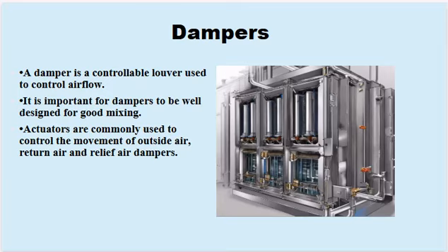They're typically installed within the ductwork to adjust the amount of air flowing to specific areas. Firstly, dampers work by opening and closing to control air volume depending on the pressure and airflow requirements. This allows buildings to maintain proper ventilation and effective temperature regulation.